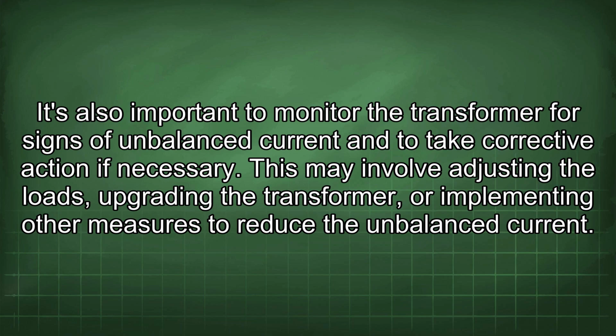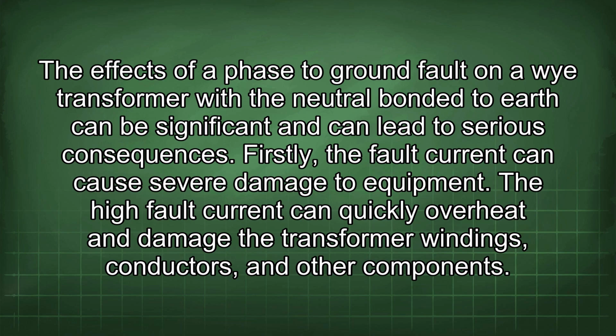This may involve adjusting the loads, upgrading the transformer, or implementing other measures to reduce the unbalanced current. The effects of a phase-to-ground fault on a Y transformer with the neutral bonded to earth can be significant and can lead to serious consequences. Firstly, the fault current can cause severe damage to equipment. The high fault current can quickly overheat and damage the transformer windings, conductors, and other components.